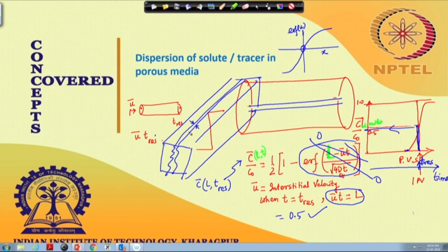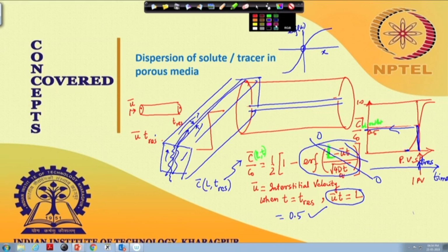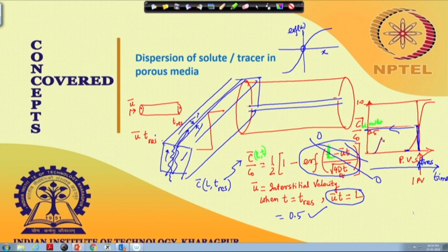So now if one fracture runs like this, naturally the fluid will have a tendency to flow through this, because it is getting a much higher permeability through this crack, through this fracture, rather than flowing through this porous medium. So what one would see in this case is a very fast breakthrough. Breakthrough means that here the concentration starts rising. So in this case one would see the concentration rising from here.